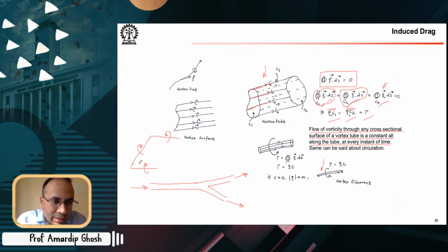However, if you have these multiple vortices, vortex contrails, that are being shed, then you see that this strength will add up on this, then this strength will further add up on this, and eventually you can have a circulation distribution something like this. Okay, so we will see these things: circulation distribution or the strength of the vortex filament.